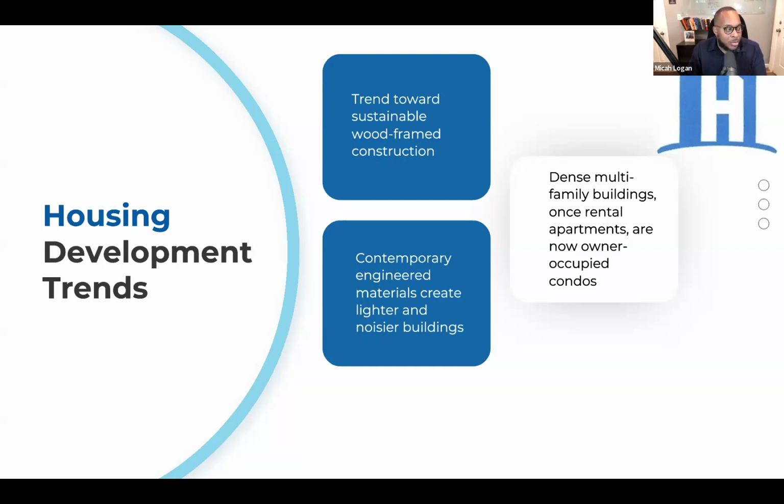Tell me a little more about the housing trends you've seen in the applications with HushFrame. It's all wood frame. Most of it is 4 or 5 stories over a steel or concrete podium, and they're dense, 50 to 200 units in the buildings. It's all light wood truss and engineered panels, and it's really loud because it's so light. Back in the 1960s, you had old growth lumber, and your ceiling would be wire and lath and plaster, very, very dense and thick.